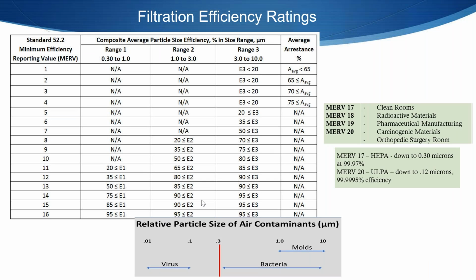That's great. To get to the realm of the 95% range or greater, you'd have to bump up your filtration to MERV 16 to get a 95% filtration, I should say, not disinfection. And in any case, we're capturing live particles in filters at this point. So a few questions arise, and that's at what point are we capturing, at what level of combination with other particles and agglomeration are we capturing?